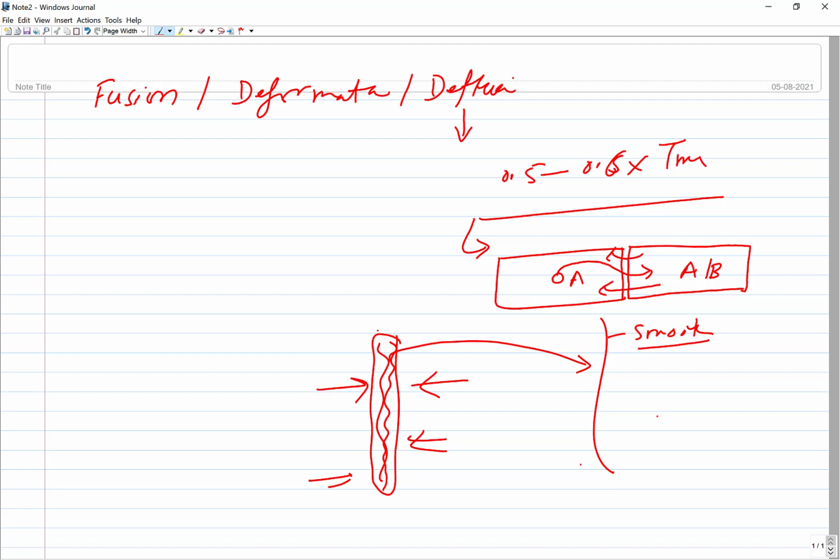You may have a very smooth surface and good temperature, but if the surfaces are contaminated with an oxide layer as small as a few angstroms, or if there are gases present at the surface, these are certainly going to hinder and obstruct the diffusion of atoms across the interface.